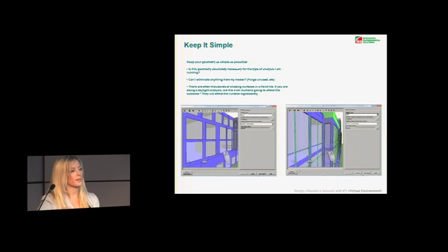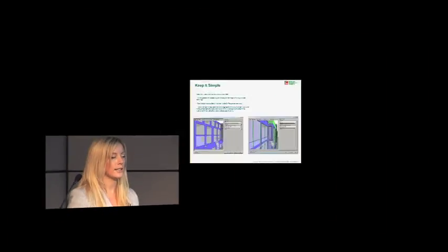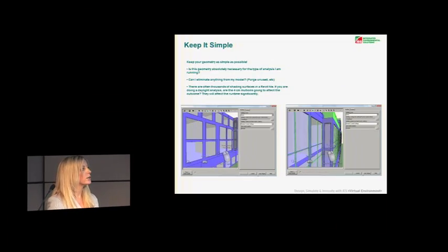The other thing that used to happen, and which is why you really need to keep the most updated version of the plugin and the most updated version of the software installed, because all of these things are consistently fixed. And that's one thing I'll always say to people: make sure that every time you're updating the virtual environment, you're doing the plugins too. Uninstall and reinstall them. And that goes for SketchUp as well. So this was a case as well where you had this 2D plane that would actually cut directly through the wall, and that would cause an issue. And those types of things have been fixed as well. So all of those intersections and problems are improved, but again, you need the updates to get that.